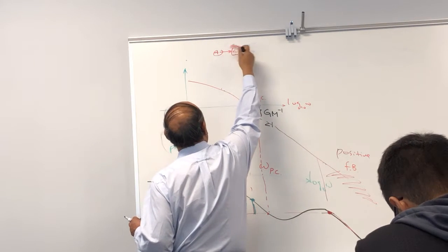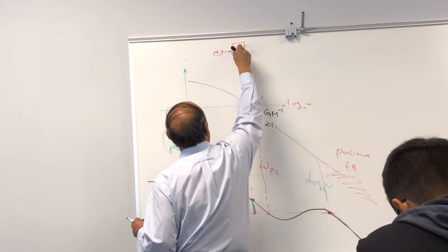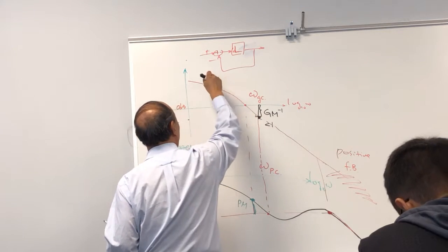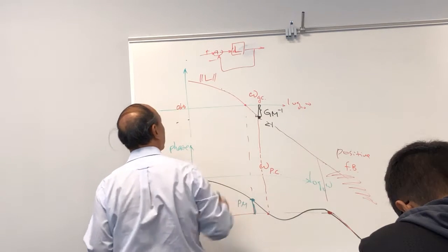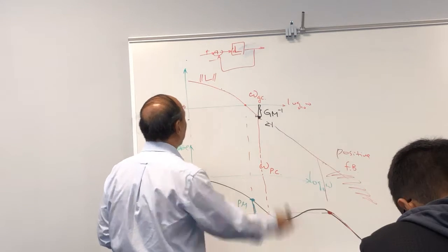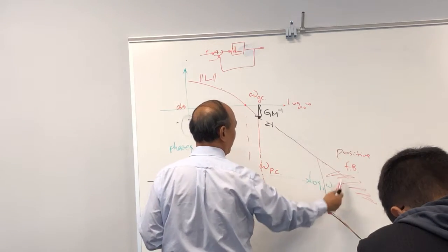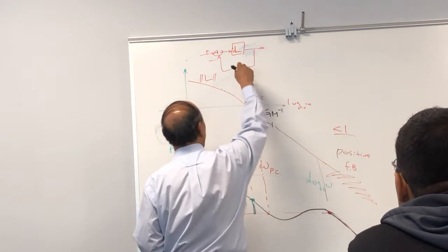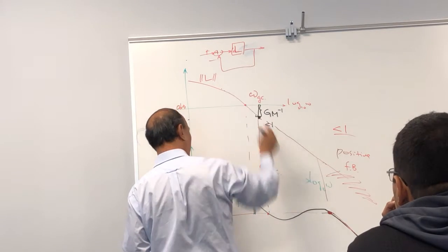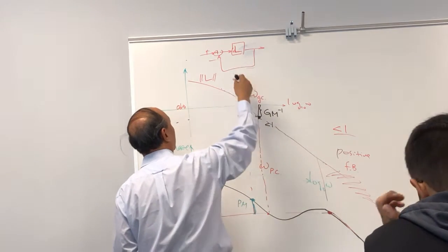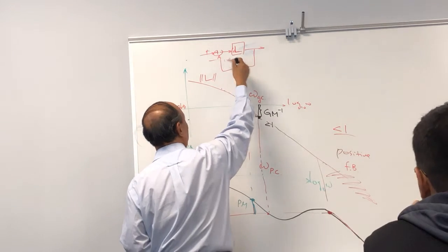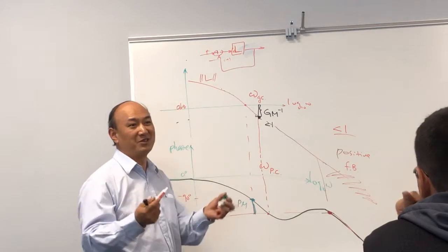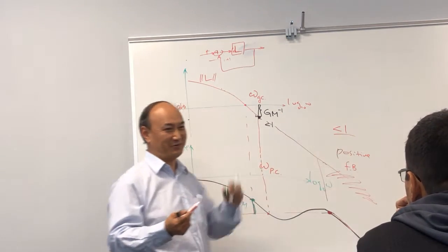Let's do error. Error is my loop transfer function. So this is my L. Okay, magnitude of my L. The signal at this frequency has a gain less than 1, although it is reversed sign. So across 180 degrees, the reversed sign becomes actual positive feedback for all the signal components here, but it doesn't matter because the gain is less than 1.